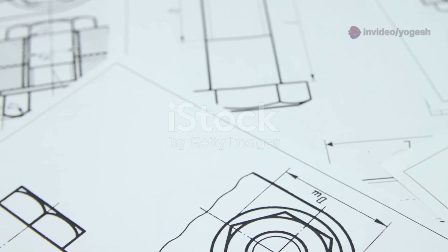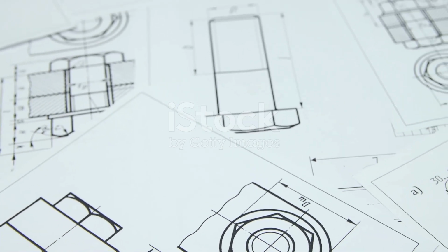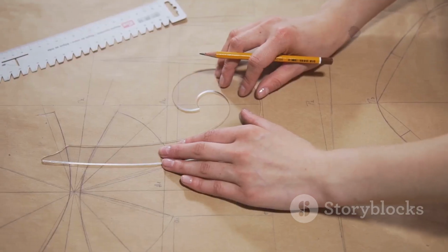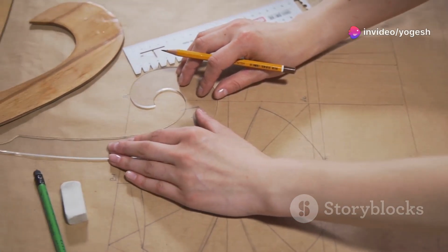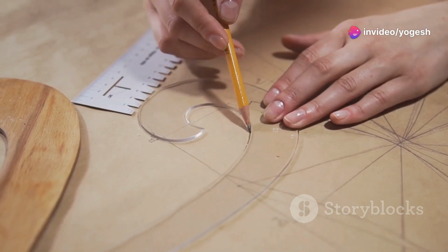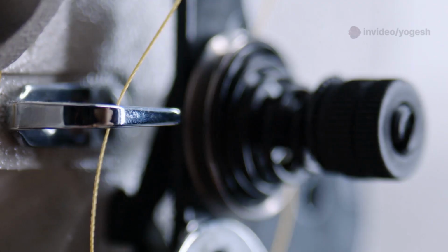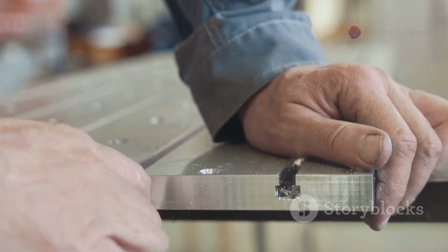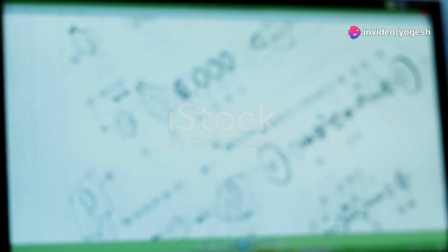Next, draw a thinner, dashed line slightly larger than the hole diameter. This represents the major diameter of the thread. The short, angled lines representing the thread crests and roots are drawn in the same way as for external threads, but they are positioned differently. For internal threads, these lines are drawn on the inside of the major diameter circle, and of course, don't forget the chamfer at the entrance of the hole.